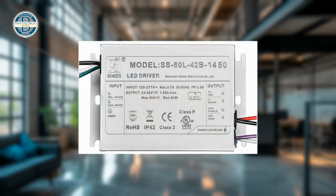Looking closely at the label of this driver, we can learn more about this specific driver. We see the input power source needs to be 120 volts AC current, and the output is 24 volts DC current. Also, we can see that the input cables are on the left of the driver, black, white, and green cables. These cables connect to the power source, typically the dimmer.